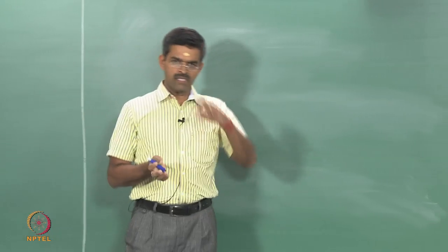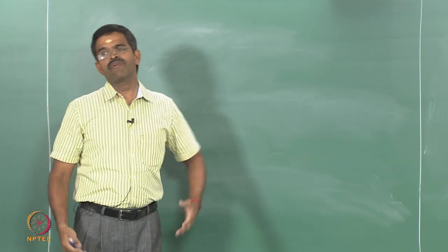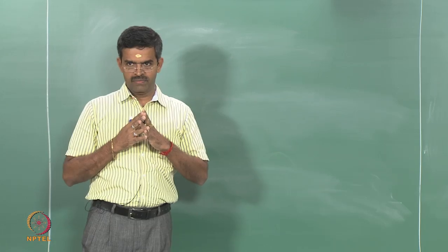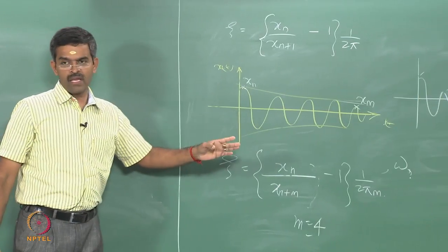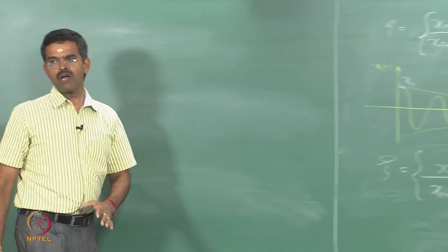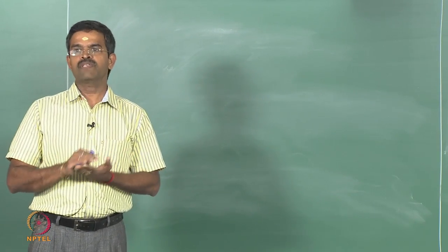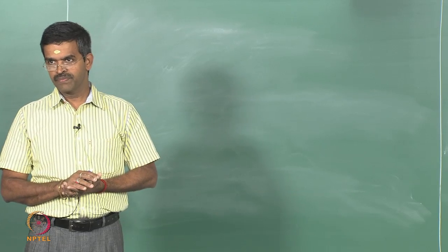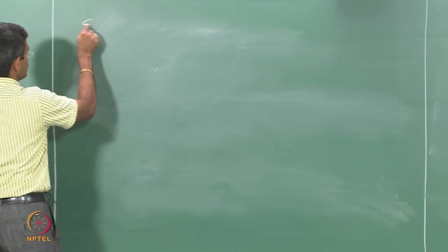So before we answer this, let us try to ask why Coulomb damping is not effective in offshore structures. We have seen the viscous damping is exponentially decaying, therefore it is effective. Let us talk about Coulomb damping. Coulomb damping is a damping developed between two surfaces because of friction. A typical plot of Coulomb damping will look like this.